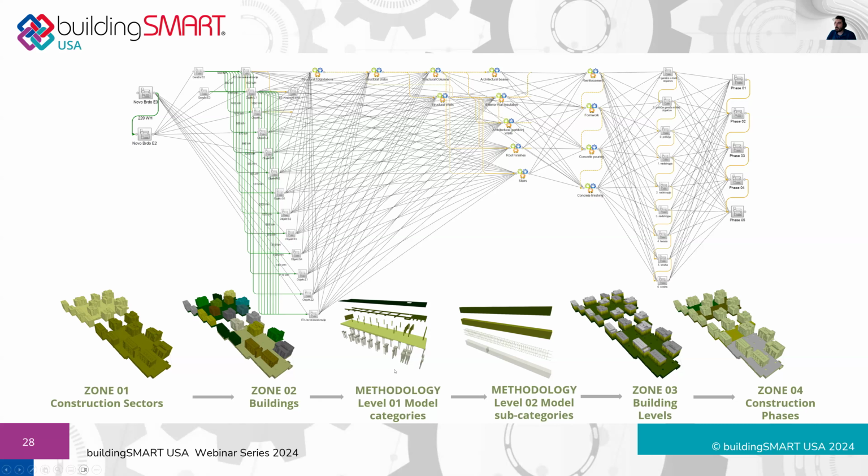So in this simple example, we would just say, okay, we're going to find groups of works: foundation. It's going to be a finish-to-start relationship between foundation and slab on grade. It's going to be another finish-to-start relationship between vertical load-bearing structure and slab on grade, and then we're going to go with the horizontal load-bearing structure over the vertical. And we're going to repeat this sequence on every floor, in every building,